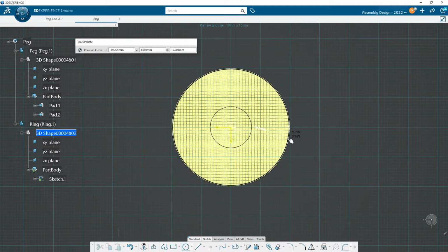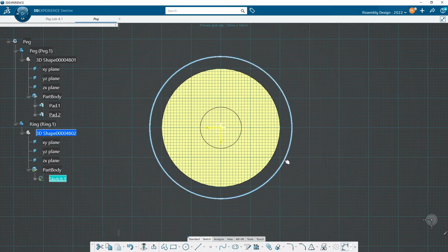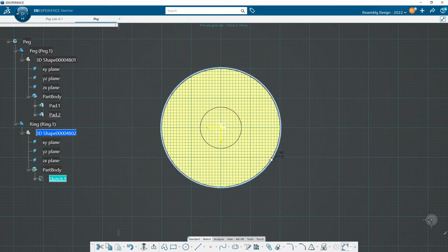This type of thing is good when you're trying to create a part that doesn't exist already and you're just inventing, okay? If you already know what the part is, you're doing everything to measurements. You also don't make it right to that edge and click it to it or constrain it to it, because that again is a link. That's a link between this part and the other part, so you don't want to do that. You don't want to make a projection of that because that's a link between this part and the other part, okay? So just know, though, that this concept of designing in context, here's what I would really do.